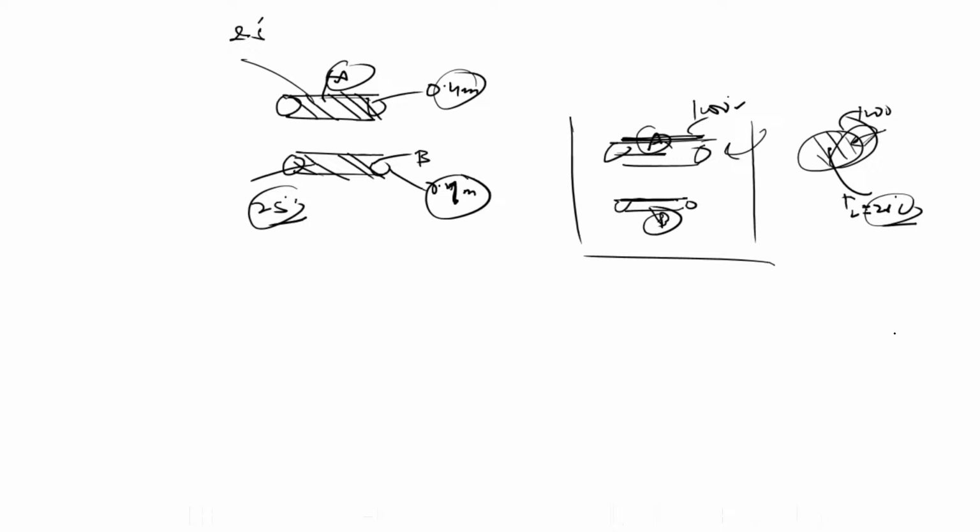So first of all, tell me, is this a lumped system? No. Because in a lumped system, temperature does not vary with space at any given time. But here it varies with space, so the lumped assumption is not valid. Here temperature is a function of r as well as time t.